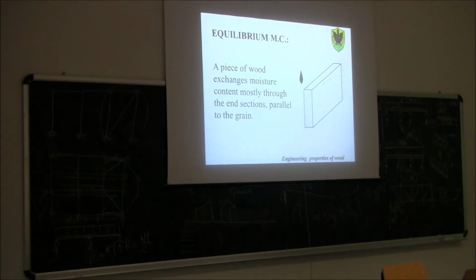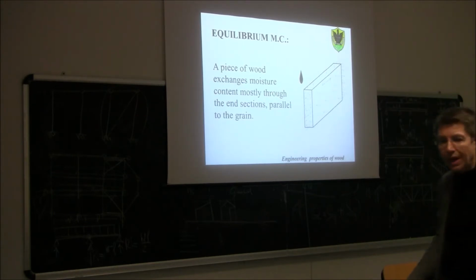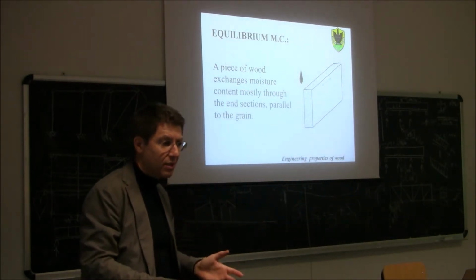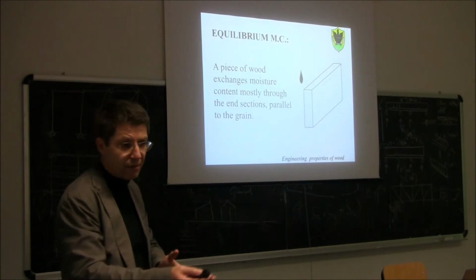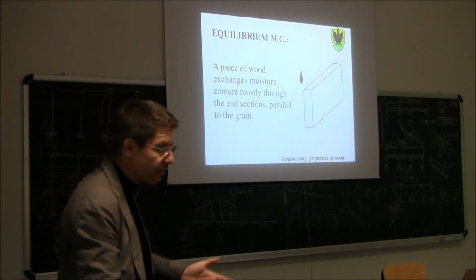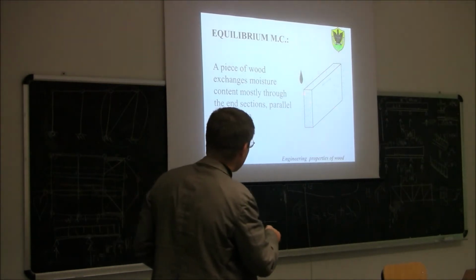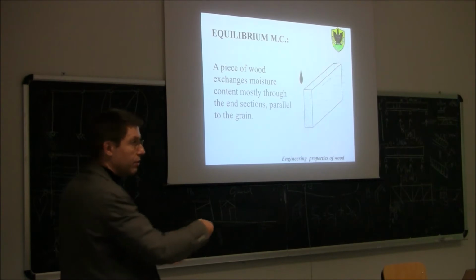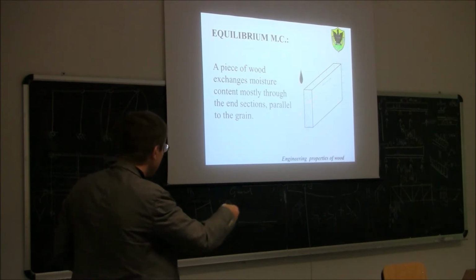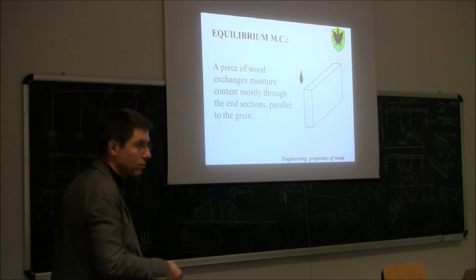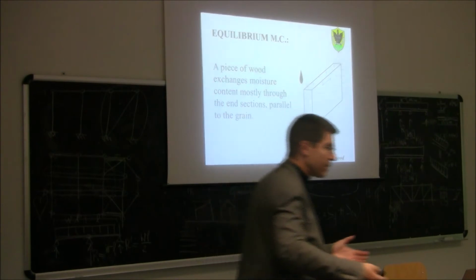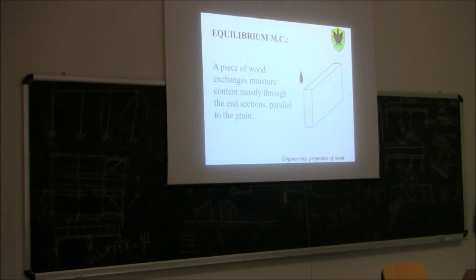So remember that if you're using wood outside, chances are that the relative humidity will be high, maybe there will also be rain, like today. In this case, if you leave this surface without any sealing, you will have lots of flow of water and moisture through it. So a good rule is to seal the surface in order to prevent the penetration of water, because there we have all the lumens of the cells.